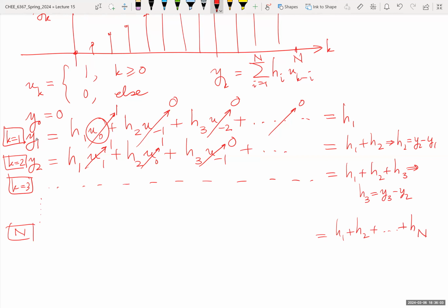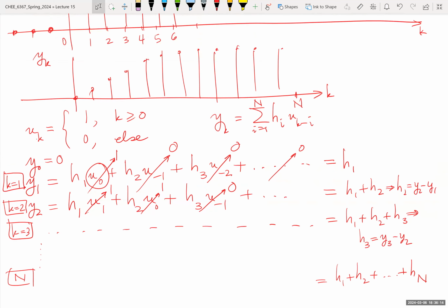And that's a simple way to get a step response experiment that you would do anyway and get values of these coefficients. The interesting thing is that when you have data here that are noisy, at least for most of these coefficients, you can draw a straight line here as you go.